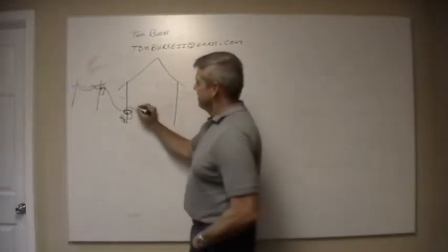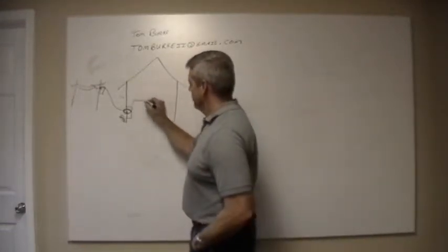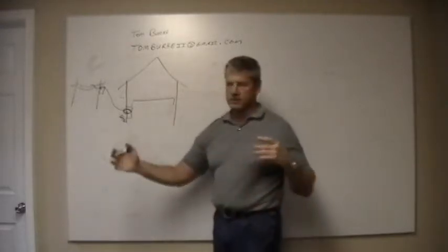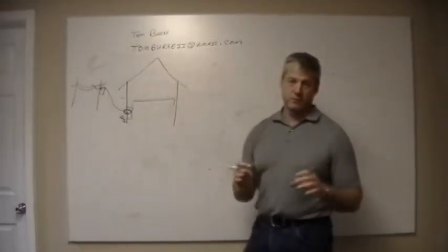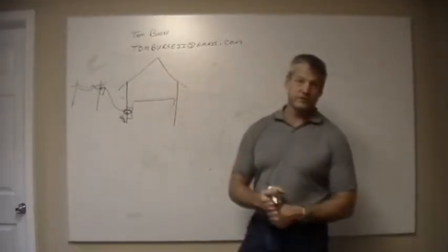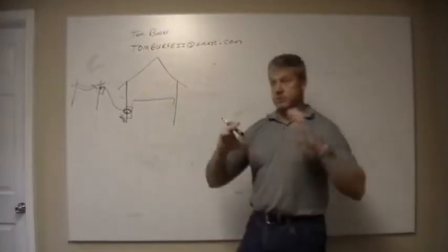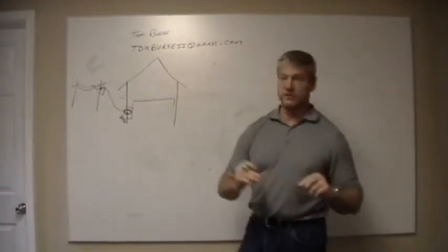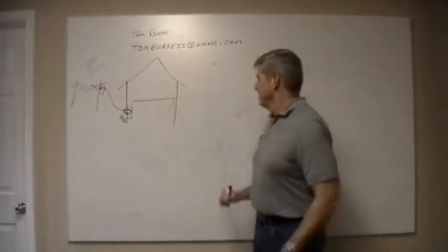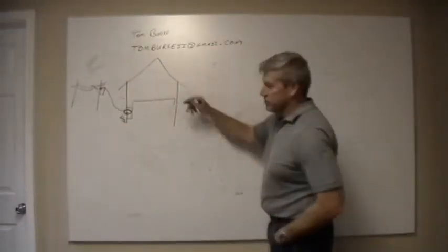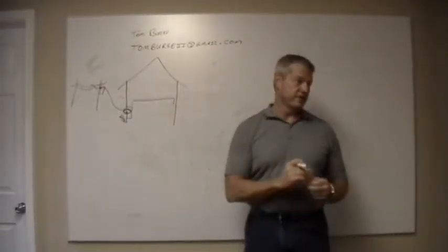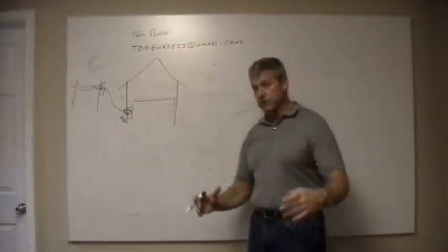It says the maximum length of wiring that you're allowed to do. Okay, I said wires have 0 resistance. That's not true. They have a little bit of resistance. The bigger the wire, the less the resistance. But the longer it is, the more the resistance. Which is why a small wire, you're only allowed to carry a little bit of current, and a big wire, you're allowed to carry a lot of current.